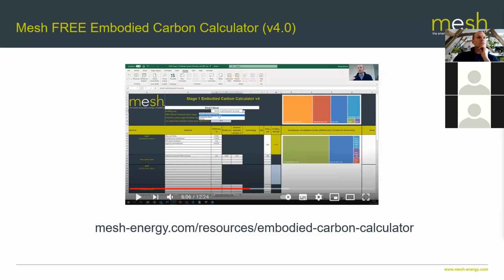Mohammed, how would the lifespan, recyclability and reusability of a material affect the embodied carbon? So this comes back, Mohammed, to the whole life carbon assessment methodology. And EPDs, although there is some comparison of EPDs that you do, the whole life carbon assessment methodology takes into consideration all of those things that you're talking about. This isn't just about digging up raw materials and processing. It's about transport, it's about replacement in use of a building, it's about demolition, it's about reuse at the end of a product's life cycle.